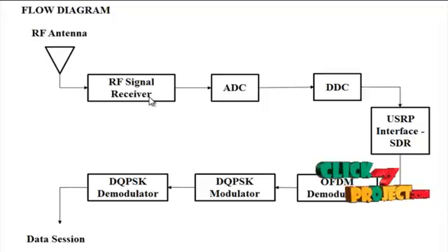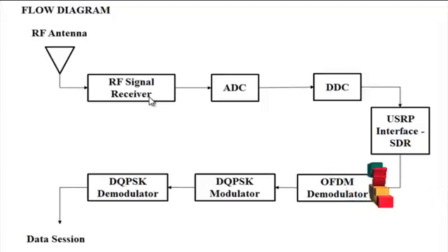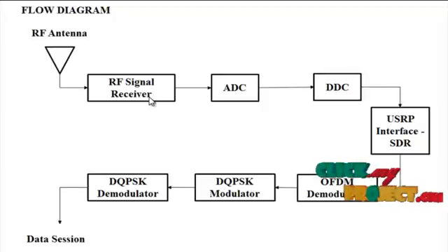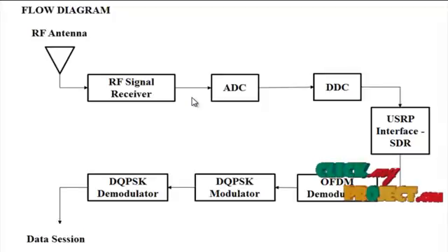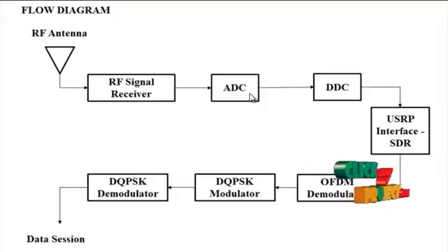This wireless communication may be accomplished through optical communication or through radio frequency communication. For many applications, the medium of choice is RF, since it does not require line of sight. RF communications incorporate a transmitter and receiver. This stability comes from a fixed crystal design, which in turn leads to a comparatively more expensive product. Next, in the ADC, that is the analog to digital converter, discrete digital conversion is performed.